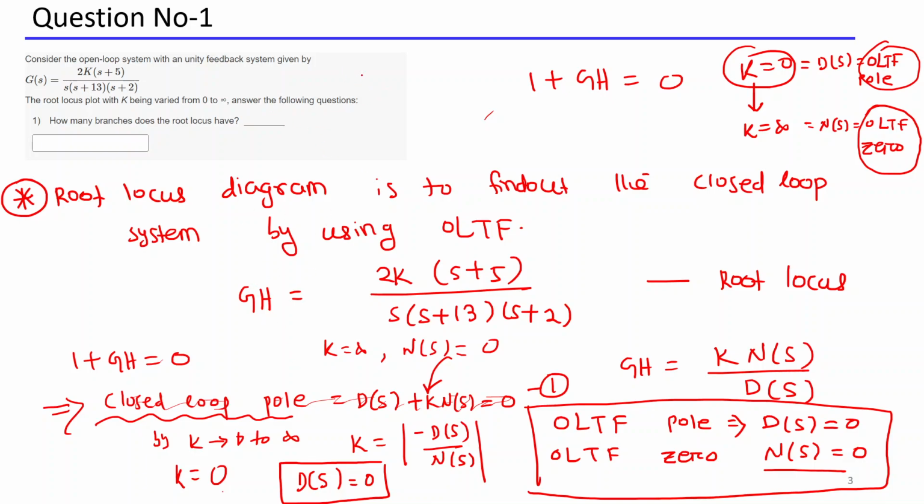So first tell me, in this question number 1, I'm just erasing the top version here. At which point will the root locus start? Root locus starting point. Can anybody tell me? From every pole location, one branch will start, sir. Okay, open loop pole location. So now how many open loop poles are there here? S equal to 0, S equal to minus 3, and S equal to minus 2.